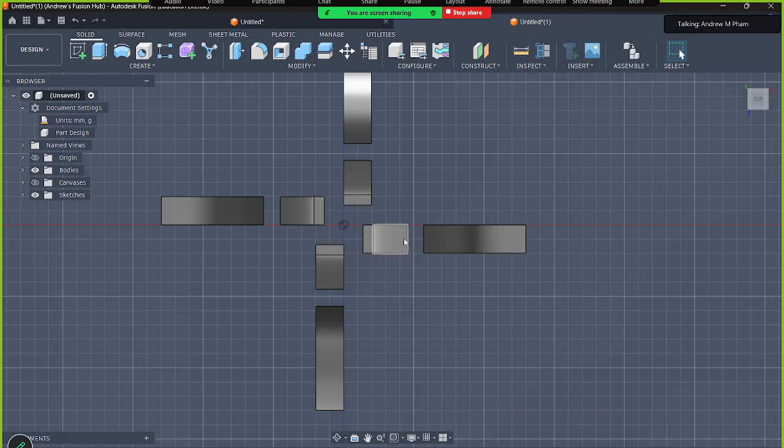If you didn't do a symmetric extrusion already, the reason why this happens, you can see this red line here, and that's where we drew our sketch, right? And that's where we're extruding from. So you can see here that we're extruding from one side only, but our axis of symmetry, where we're patterning everything, is the origin. So it'll create this strange offset here.